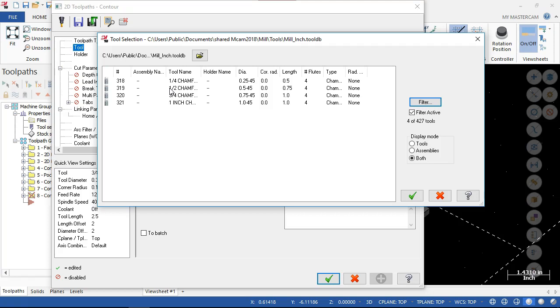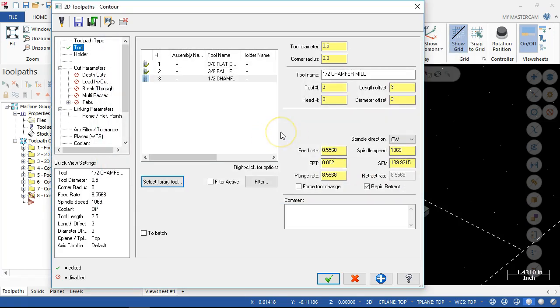100 thousandths, that's going to be pretty close and quite heavy for a 1/4 inch. I don't think the ½ inch. I would still say load the larger tool into the program, and then if we need to, we could go out on the floor, grab a 3/8 or a 1/4 inch, and see what it does. It's still programming to the tool and the depth. So